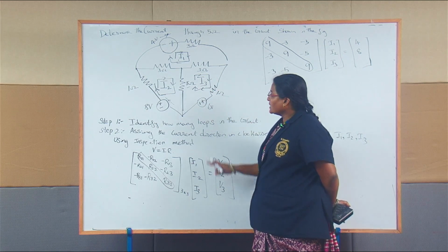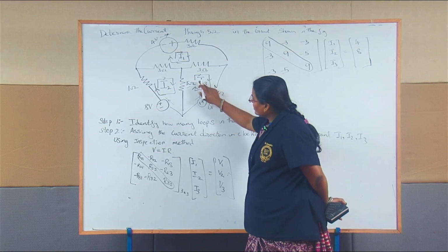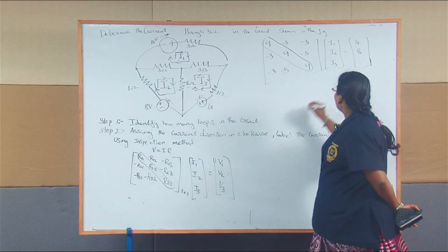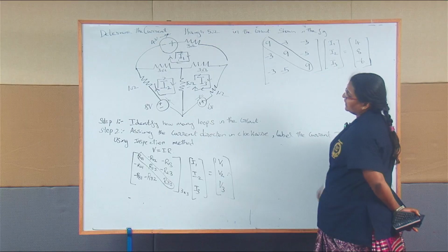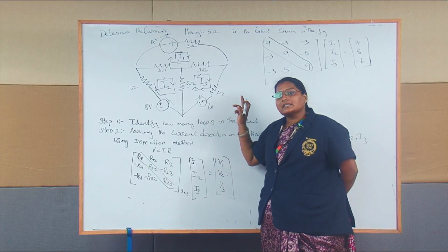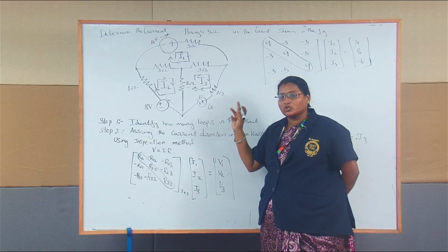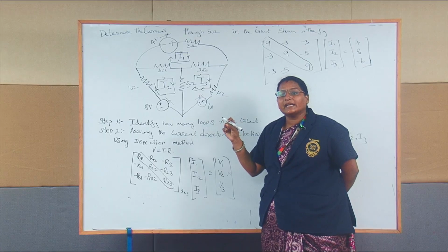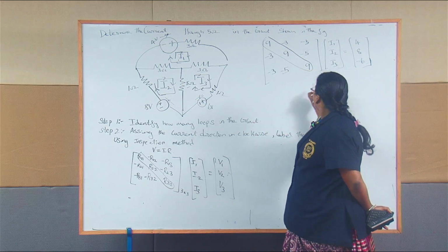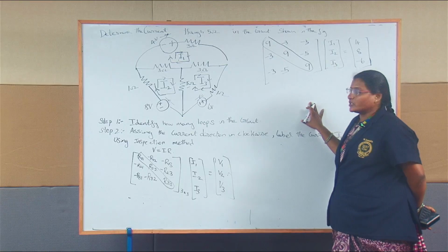Okay. Next, the source voltage present at loop 3. So in loop 3, the source voltage is 6 voltage. The arrow shows that it goes from positive to negative, so it's nothing but minus 6 voltage. Each and every time, for the voltage source you have to check the assigned direction. If the arrow ends at positive, you have to take positive voltage. If the assigned direction ends at negative, you have to consider negative voltage. So this is how we form the matrix using the inspection method.